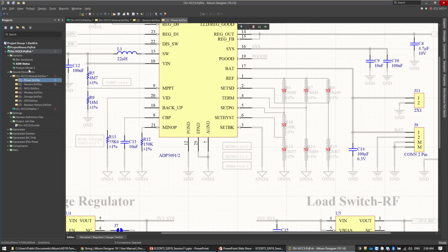And now it's done. If you go now and generate the bill of material for this variant, these will not be on the bill of material. And when you generate the pick and place file for the pick and place machine, these also will not be part of that file. And that is basically how you can define variants and change them. Now, if I need to get these back to be assembled, same thing, you just toggle the status of these parts very quickly.